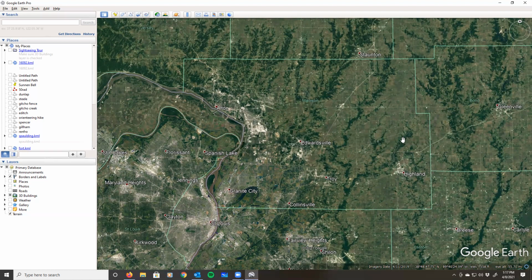The only thing you would have to define at that point is a point where this central meridian and the latitude line crisscross, and establish a certain coordinate value at that point.